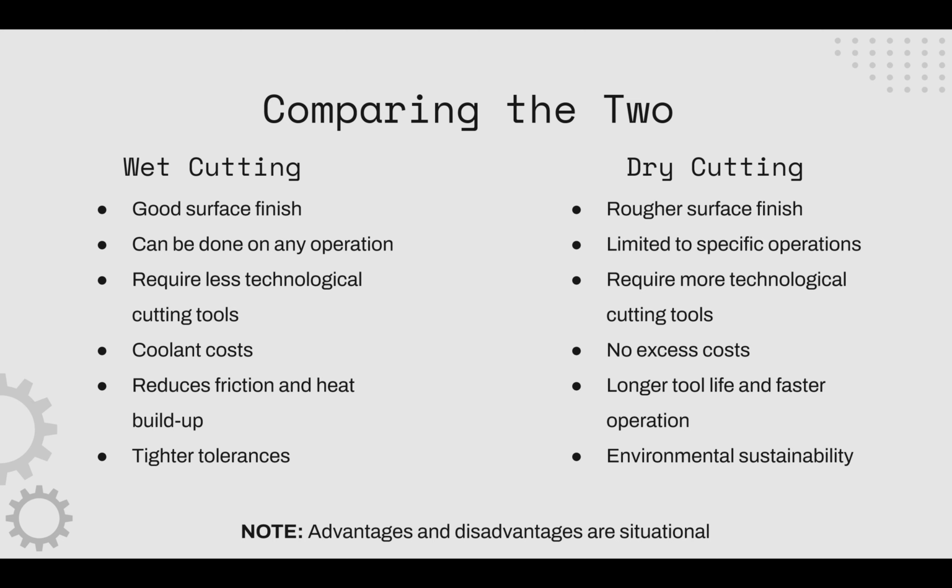Tighter tooling tolerances can also be achieved since thermal expansion has no chance to play a role with coolant. However, the tool will experience constant thermal shock when performing an operation like milling. While coolant may increase tool life since there is virtually no friction, it can decrease tool life from repeated thermal shock.